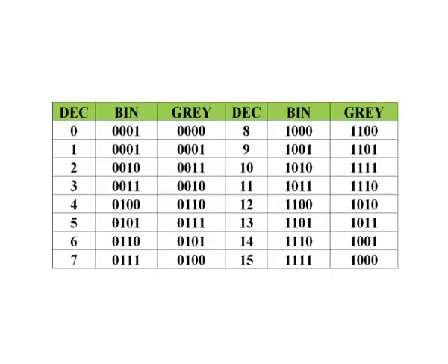Owing to this feature, the maximum error that can creep into a system using the binary Gray code to encode data is much less than the worst case error encountered in the case of straight binary encoding. This property is important in many applications such as shaft position encoders, where error chance increases with the number of bit changes between adjacent numbers in a sequence. The table here lists the binary and Gray code equivalents of decimal numbers from 0 to 15.